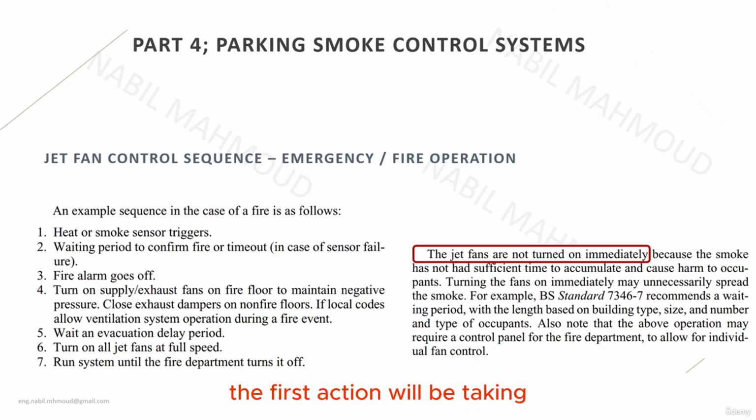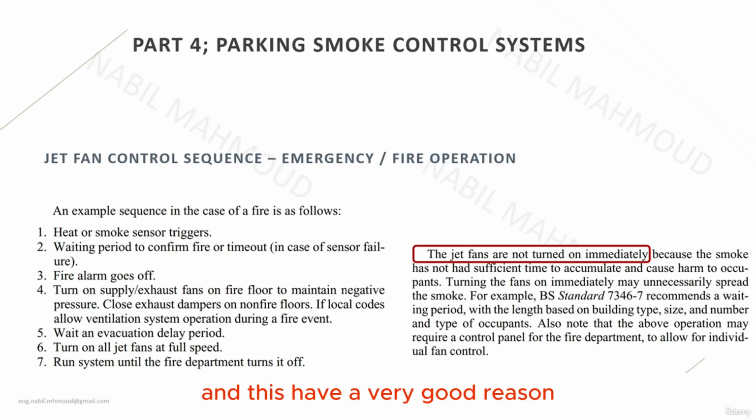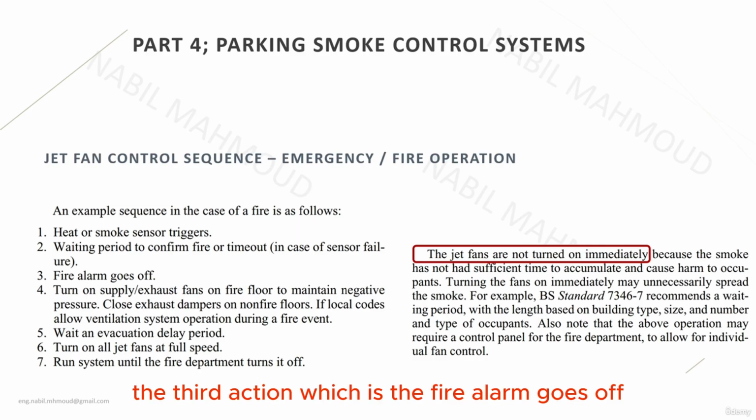The first action we'll be taking is that the heat or the smoke sensor will trigger. The second action is the waiting period. And the waiting period means that the fan will not activate instantly. And this has a very good reason, I will explain in the following paragraph. The waiting period is required in order to confirm if the sensor is faulty or if there is an actual fire scenario. The third action, which is the fire alarm, goes off.